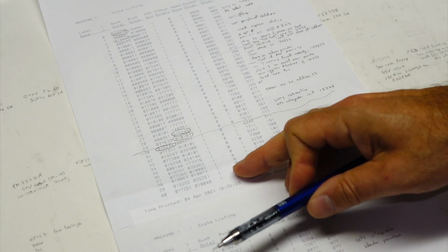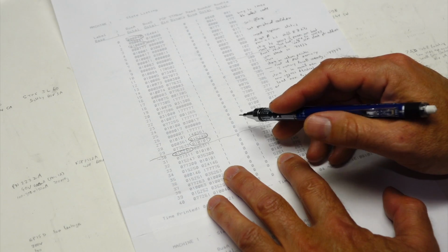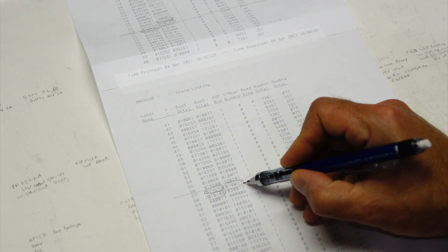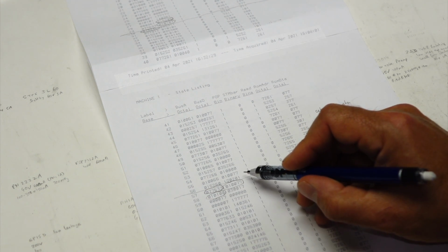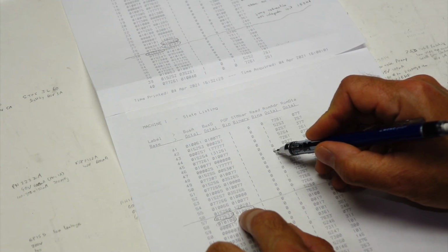So if my theory is right about the RAM controller just not feeding the correct address to the RAM, actually feeding only one address, 0, that would explain why the memory checks good, because we check only the position 0, right? No matter what address comes in the chip, what is given to the RAM is always 0, so that's always good. But I should be able to check if we are shoving everything into the same address. Then when I read the wrong return, where is it? It's over here. That number 010077, which I thought was random, should not be random. It should be what the last address to RAM was, and it's all shoved into 000. And so I just need to see what the last write was. So it would be, it's right here.